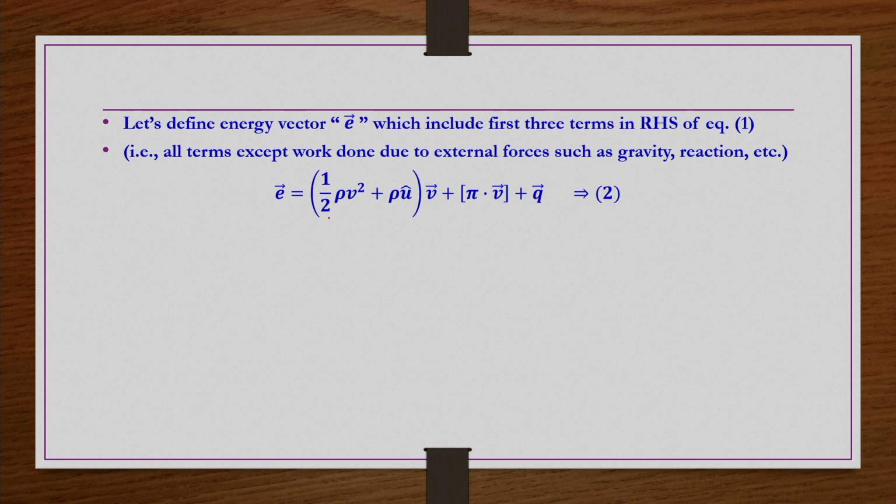So, that is the net rate of addition of internal energy and kinetic energy because of the convection, plus the net rate of heat addition because of conduction, then the rate of work done because of the molecular transport mechanisms, something like molecular stresses. These are the 3 terms. All these 3 terms are now included here. Okay. So, why are we writing this? Because we are going to do a balance.